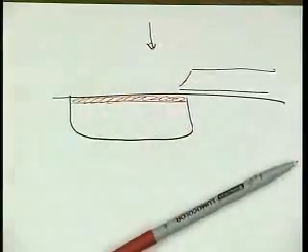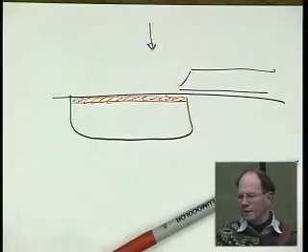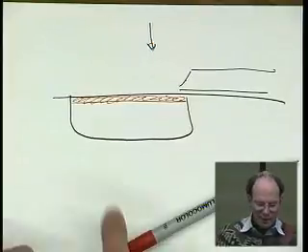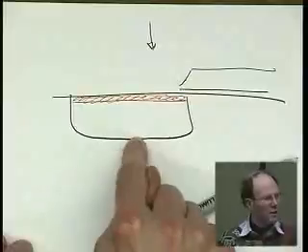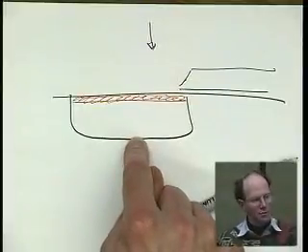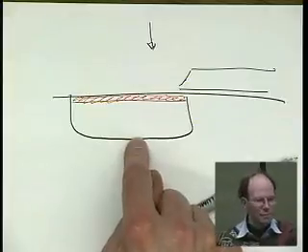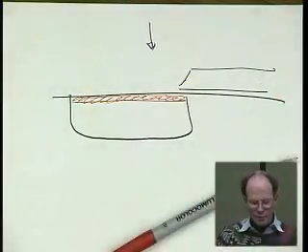It's some kind of a combination of the two things, with the net effect that it has higher sheet resistance than the metal, but lower sheet resistance than the silicon. Okay, and I guess the reason they do it like that is that it's kind of tough to have a junction in a transistor made out of a metal, right? It's no longer a transistor, so the silicide is kind of attractive there because it leaves you with the transistor.